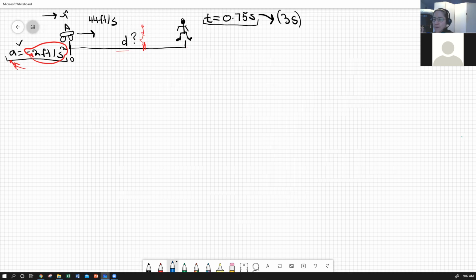It can change without you meaning to change it. So dead loads are things like weight or very measurable wind strength. Live loads are things like traffic. Somebody could suddenly start driving something way heavier than you ever thought somebody would drive over your bridge. You put bigger safety factors on things you're less sure of.